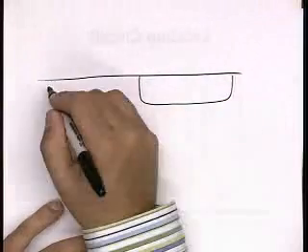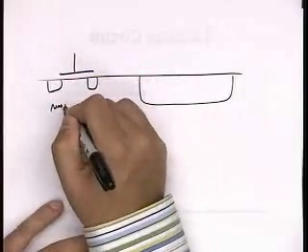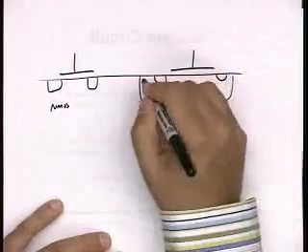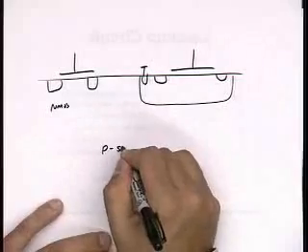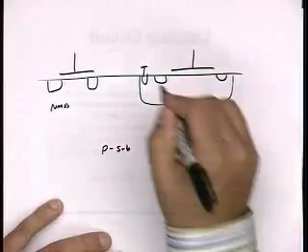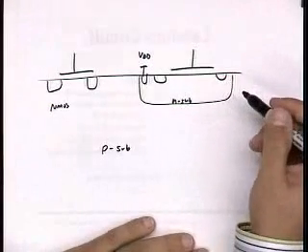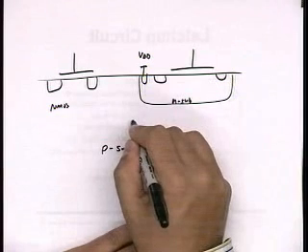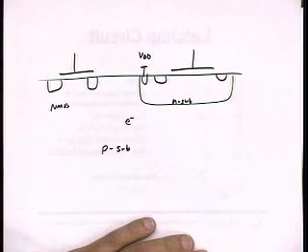So let's say I have my NMOS device and my PMOS device. So this is a P substrate. This is an N sub. It's connected to VDD, so I reverse bias this junction. And let me just start out with an electron. Let's say that somehow or another I've got an electron in my substrate.